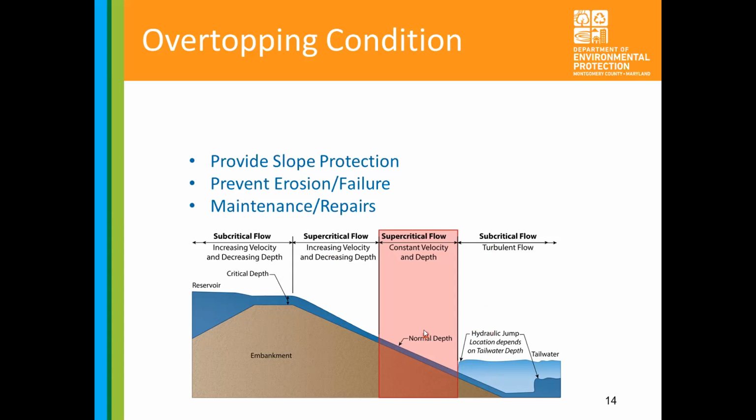So what we are concerned with in our cases is this area here where it's supercritical flow, because the higher velocities mean there's more energy and it has higher shears, which we'll get into later. Basically, this area is more susceptible to erosion. I guess this is the highest point of our stresses that we care about in terms of protecting.